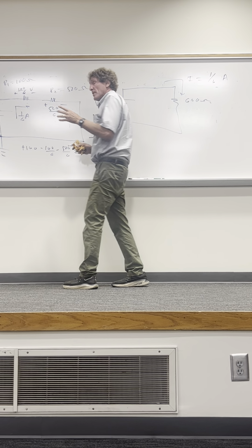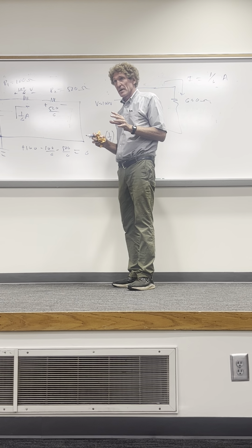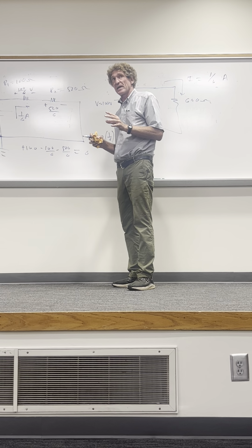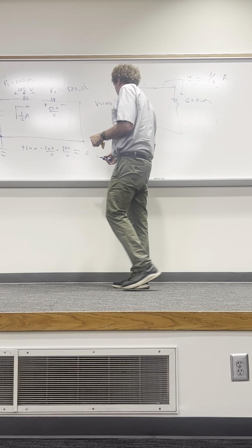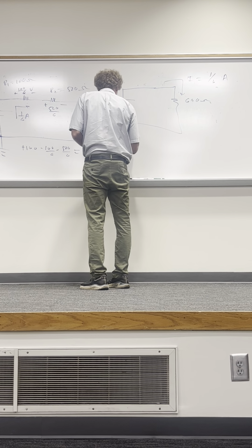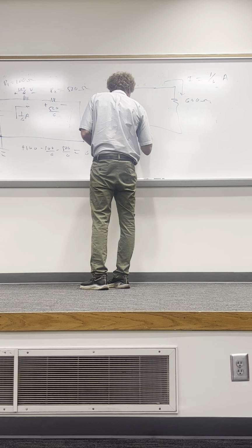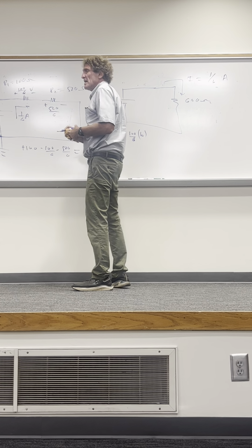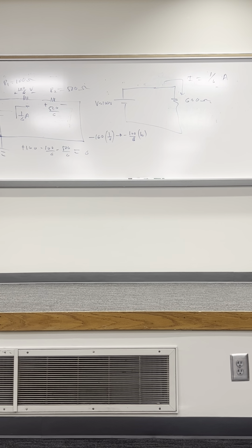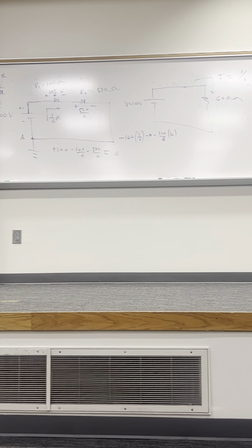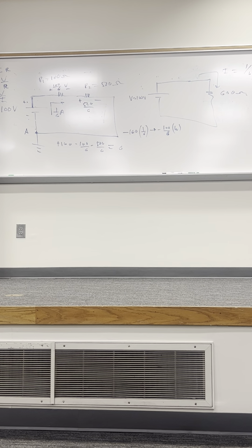Now that, by the way, will be the total power supplied in the circuit. Y'all see that? Doesn't matter how many other resistors are there, they can't supply power. So the amount of power supplied is going to be minus 100 over 6 watts of power. You would never see a negative sign. What they would say in the real world is it would supply 100 over 6, or 50 over 3, or you can break it down any way you want, watts of power. Y'all with me, class?